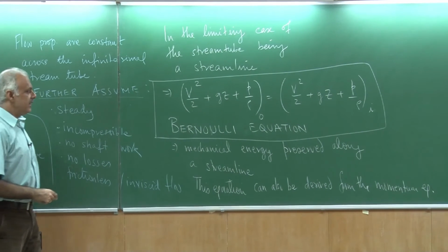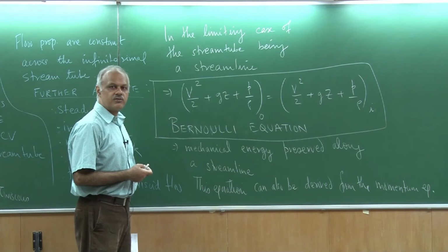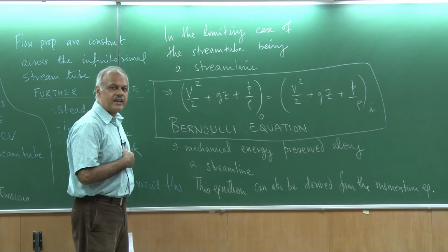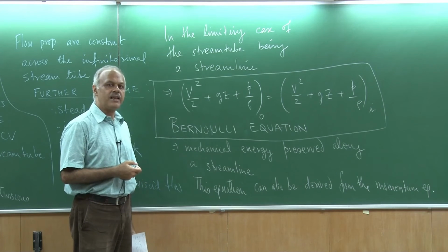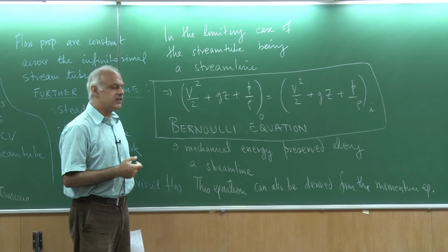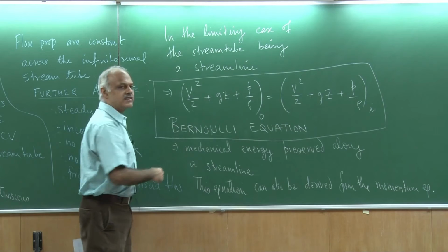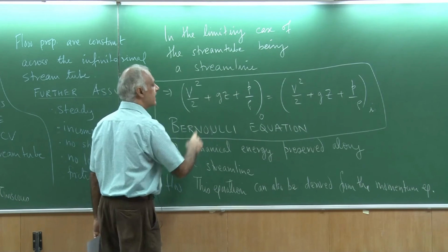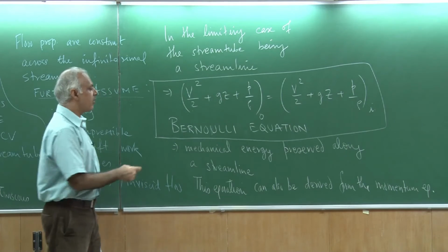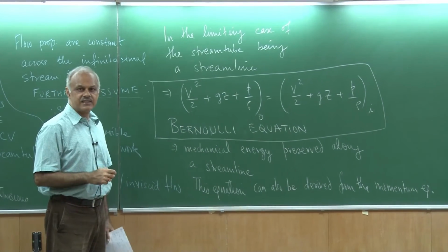It is different from the regular balance that you are aware of. So, if I take a projectile and I hurl it and I talk about the mechanical energy balance, and if I neglect the air resistance and so on, then usually it is a balance between the kinetic energy and the potential energy. That is what you already know. The difference here in a fluid particle is that a fluid particle also has to do some work against the pressure that exists in a fluid.